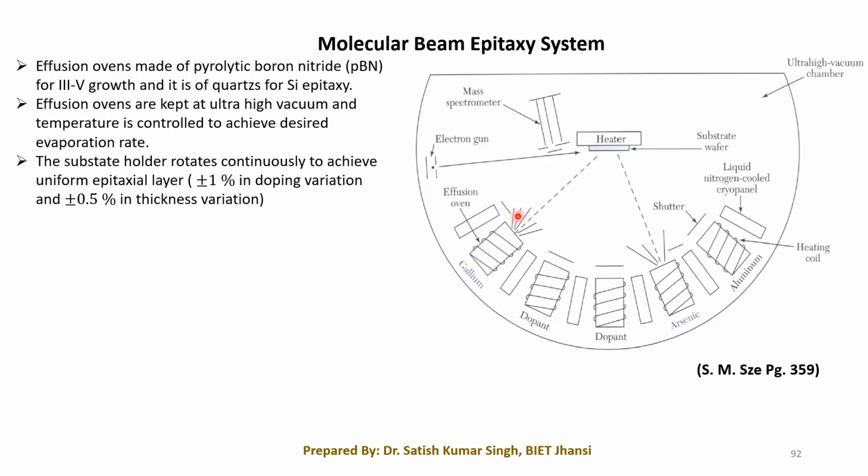to have these chambers. You can see it is a resistance heating method we are using within these effusion cells. We have the gallium, then we have the dopants, then we have the arsenic material over here, then we have the aluminium over here. So this way we can keep our different sources. Those sources can be anything that we want to grow, or that we want to dope.